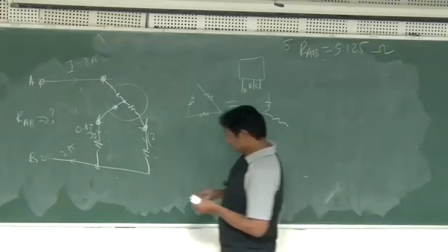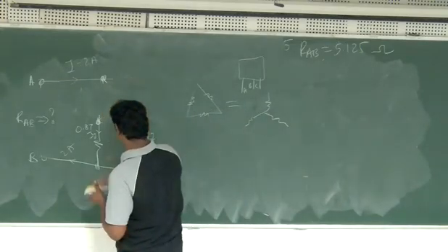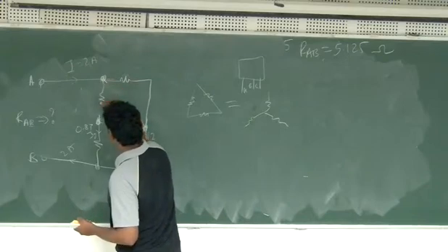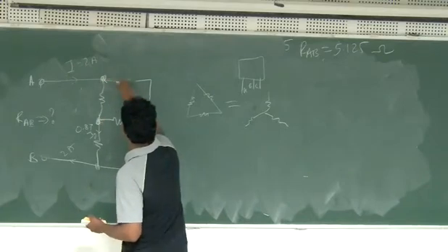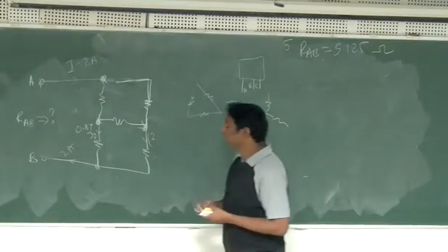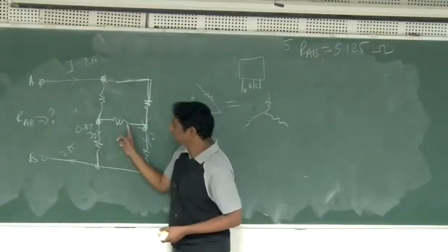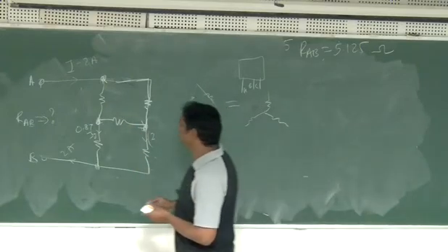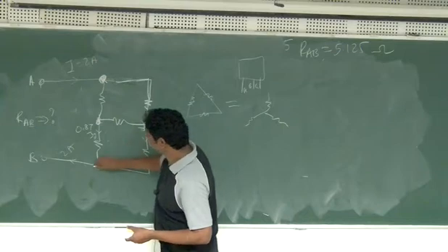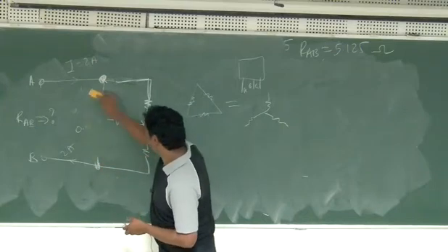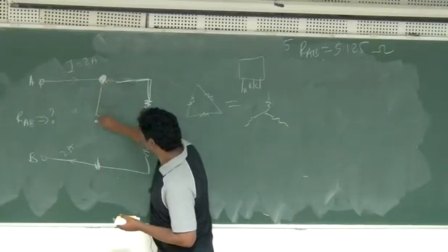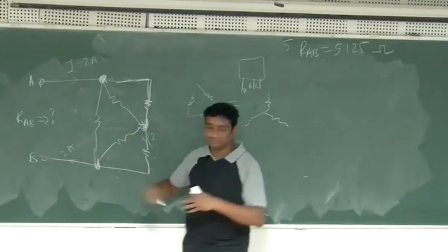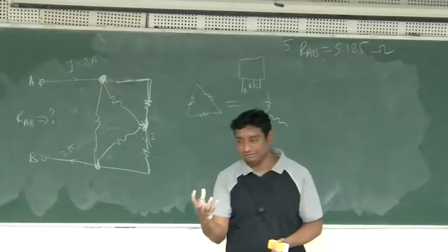We'll do that. Now, before we go forward, I go back to my earlier circuit. It was like this, right? It was like this. Okay. I can also see one star here. So this star also I can convert to delta. So what I can do is take this point and this point. Remove all the 3 and then make it into delta. So this is R1, R2, R3, some 3 different values. You have to calculate the equivalent values.